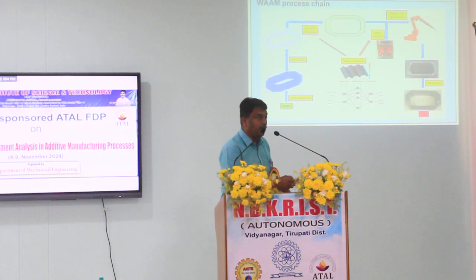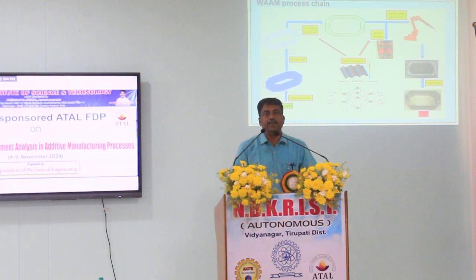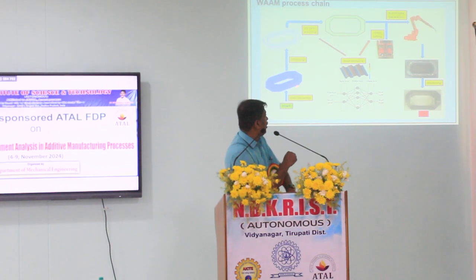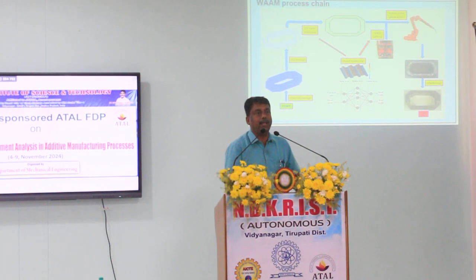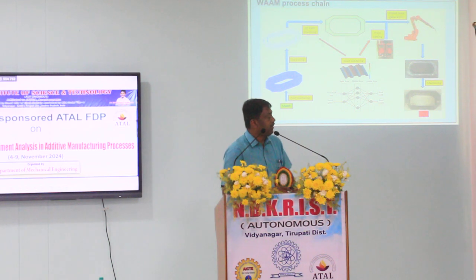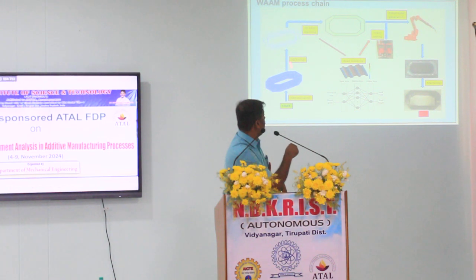Good. So again, quickly to brush up, what do we do in the process chain? Once we identify the complexities, the robotic program has to be generated. We start with a CAD drawing, you know that, right? Converting that into an STL file. Now we are also moving towards the AMF file because of inherent problems with the flat faceted STL geometry. So now we are also introducing AMF, additive manufacturing format, where we can also negate the curvature of the contours. Once we have an STL file generated, we slice and the parts are generated.